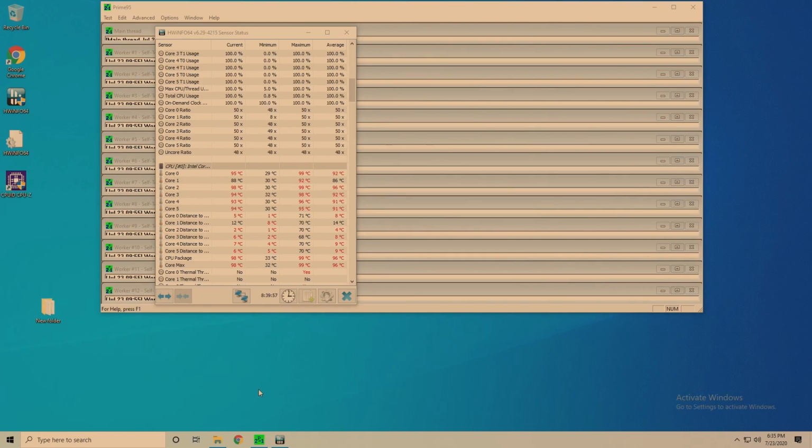Alright, so we'll let... Okay, well, we're here at 8 hours, 39 minutes, and we're completely frozen. So the 48X uncore multiplier was not stable. That's why we test for so long, because after 8 hours, everything looked fine, but now it's frozen. So we're going to go back down to 47. We know 47 is stable because before we caught our mistake, we had it running for over 12 hours without any issues. So we're going to go down to 47. We're going to lock it there, and we're going to call that complete for our CPU overclock.